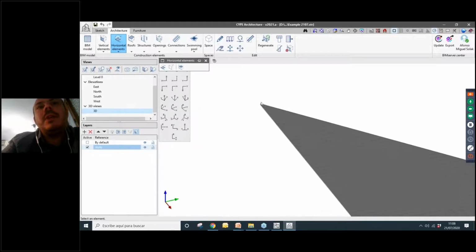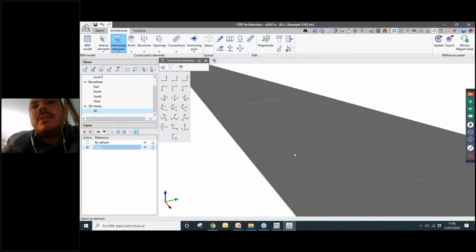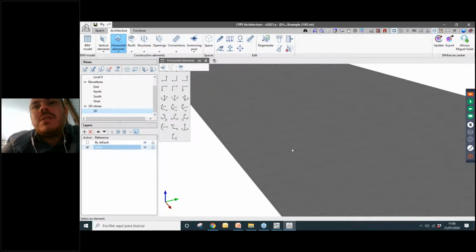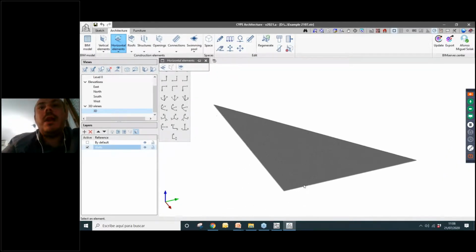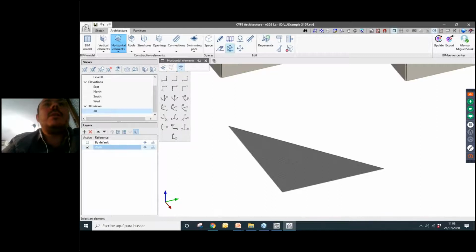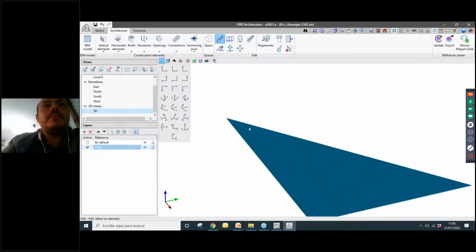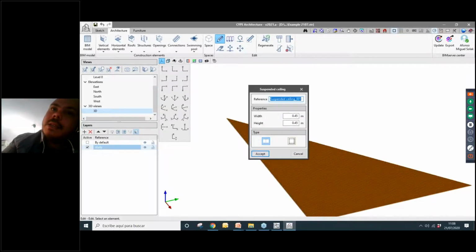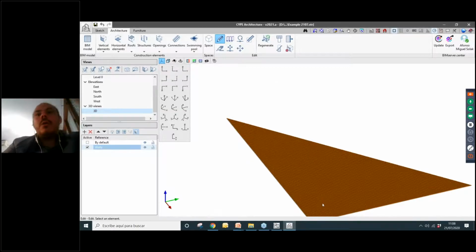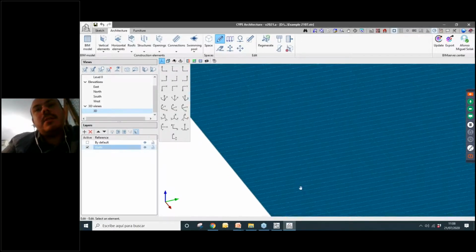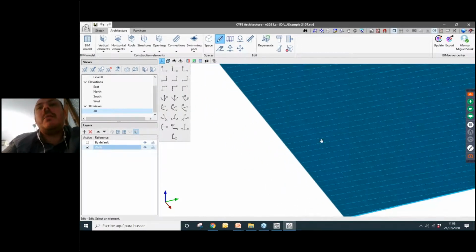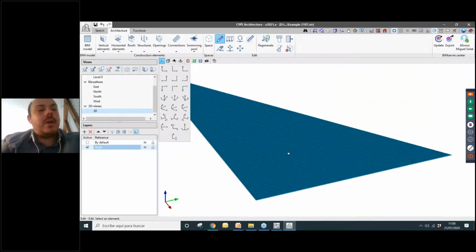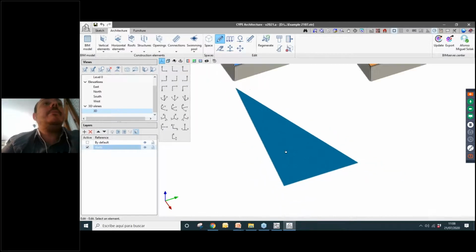Okay, so I use that point. As you can see here, we generated the suspended ceiling with all the modulation of this suspended ceiling. Actually this is a huge panel that we created here, a huge surface with a lot of panels. Then we can change. We have two types. We have a type that is continuous or removable. If we change to the removable, we'll see these little rectangles here. And we can change the size, the dimensions of these modular panels of the suspended ceiling.